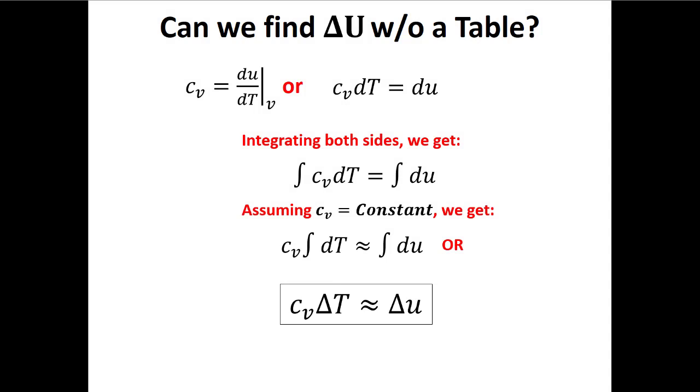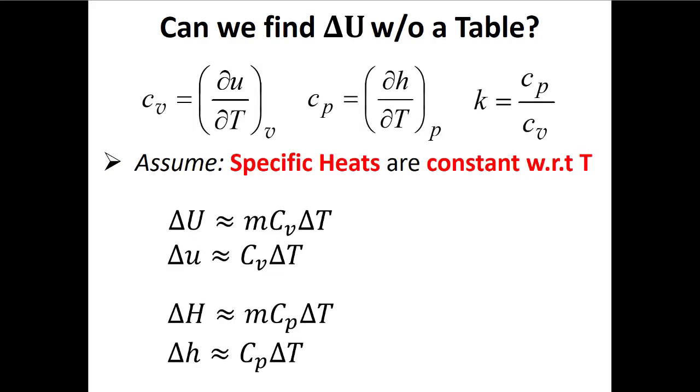It totally breaks down if we start to boil our liquid. This equation is good if the two state points you're talking about are both liquid state points. So you're going from one liquid to another liquid, right? Maybe you're changing the pressure or you're changing the temperature. You can use this equation. But it doesn't work if you start to boil your substance. So this equation is only good if we have liquids or solids. It doesn't work for vapors or the transition from liquid to vapor.